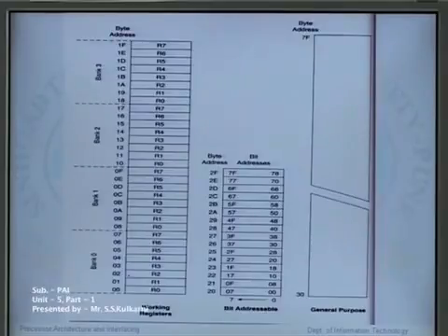The bits RS0 and RS1 in the program status word determine which bank of registers is currently in use. Register banks not selected can be used as general purpose RAM. Bank 0 is selected on reset.